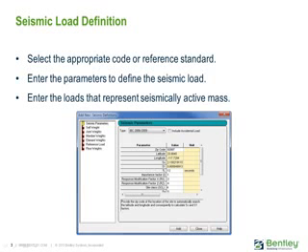STAAD.Pro has the ability to generate loads to perform a seismic equivalent lateral force analysis according to a number of different codes and reference standards. In STAAD.Pro, load definitions are used to add supplemental information before the load can then be applied to the model. When it's applied to the model, it is actually applied in the form of load items and load cases, which we'll get to in the next video.